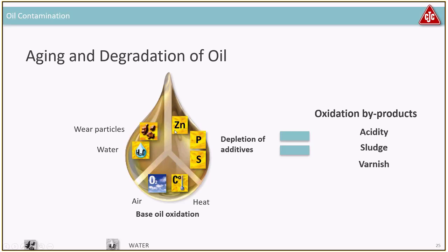So the particles will take some of the additives. You need to get the particles out as fast as possible. The more particles you have, the more additives you will deplete. So when you're depleting your additives, you're getting a shorter oil life, and you need to change the oil.